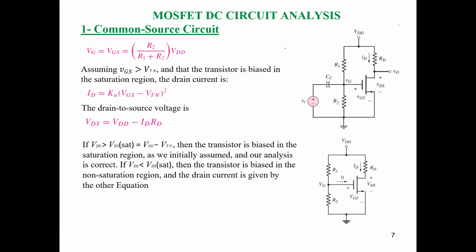Switch means control the switch. You apply a certain pulse to VGS in order to allow drain to source current to flow. And if you apply 0 VGS here, the current output will be 0.